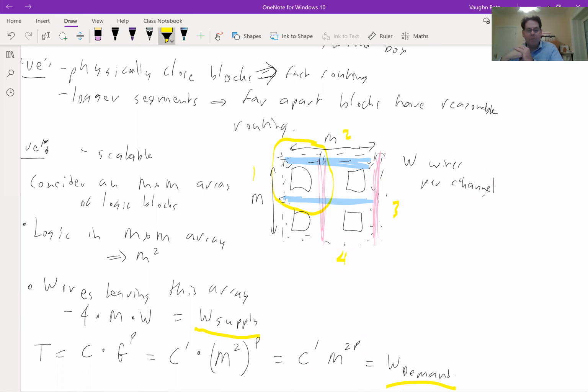So they make a very highly optimized layout of the unit of the chip that I just drew a circle around, and then they stamp that out over and over again. Making a really optimized layout of an entire FPGA logic block and all the wiring that goes along with it is actually quite time consuming. So this will take many person years of effort. So they'd rather not change the channel width very often, because if I change the channel width, and I make it wider, not only do I lose efficiency, I actually have to relay out this basic block.